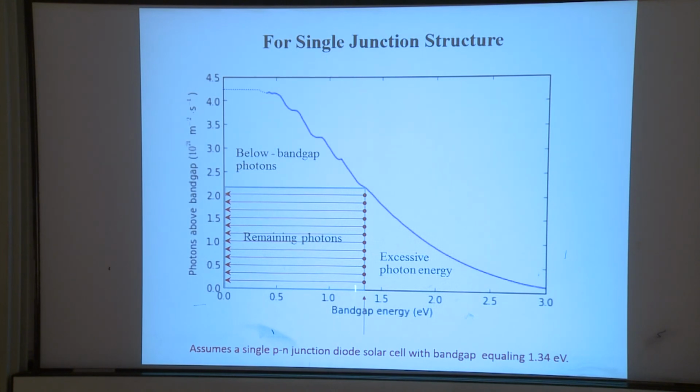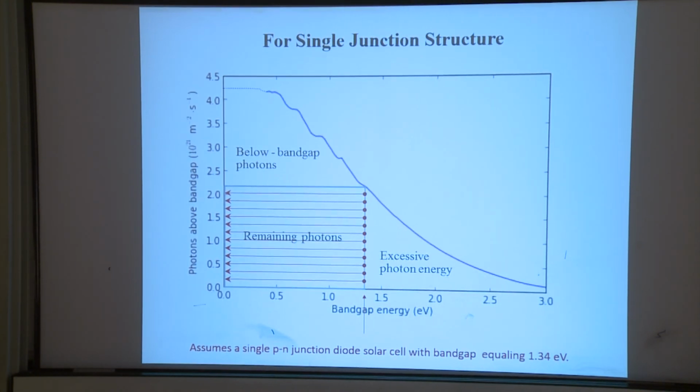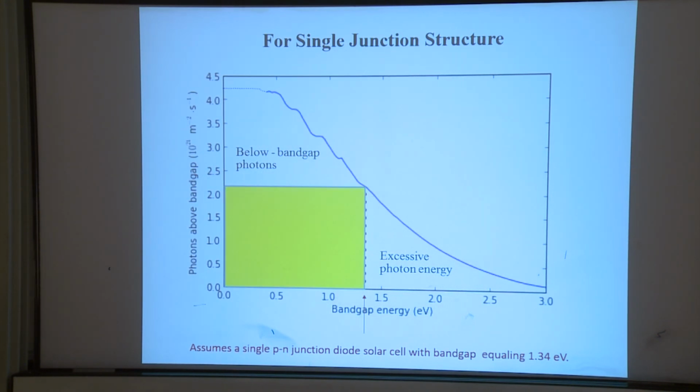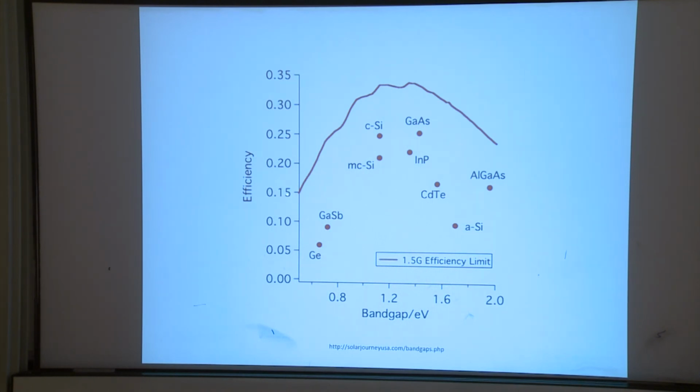So you need to choose the best band gap. What will be the value for the solar spectrum? It is about 1.1 eV. So you need to choose a semiconductor band gap around 1.1 eV. That gives you the best solar light collection efficiency for power generation. So you cannot choose any semiconductor. You can only choose a semiconductor with a band gap very near to 1.1. All right? So this will be the maximum efficiency that can be collected by a semiconductor.